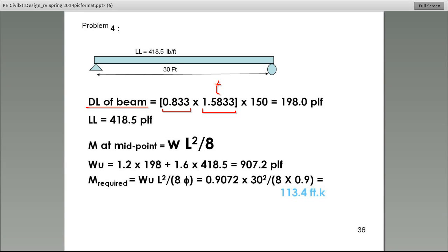All right? So the dimensions, again in terms of feet, we're multiplying by 150. Who can remember why 150? We talked about this earlier in this presentation. Remember when I said normal weight concrete weighs somewhere between 140 and 150 or 155 PCF, pounds per cubic foot? Here, we're using 150. Now, you may ask, on the test, what should we use?